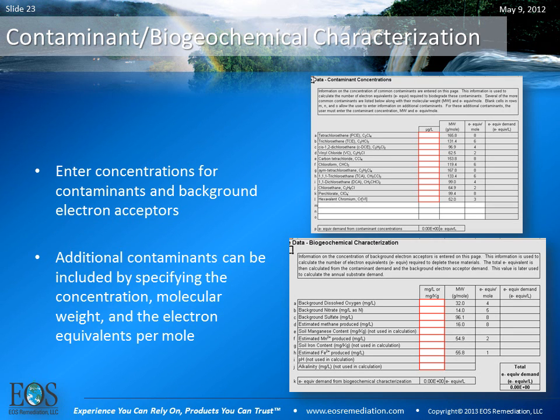Again, this is also an input parameter, your contaminant and biogeochemical characterization. You're going to need to provide your aqueous phase PCE, TCE concentrations, all the daughter products. You also have the option to add in other contaminants that you're interested in in those blank spaces there as well.